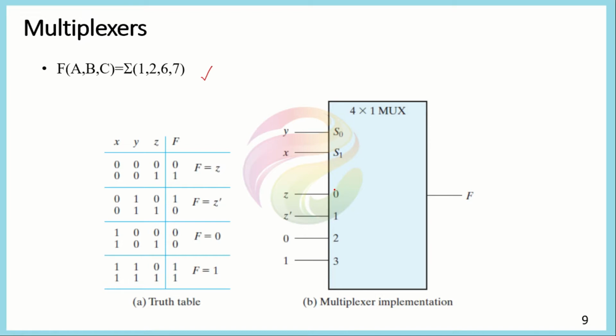Now we will see how we can use this multiplexer to represent this Boolean function. For the time being, just ignore these expressions and focus on these input combinations. We can see that there are 2 bits of selection line. For the multiplexer, we would have 4 different combinations.